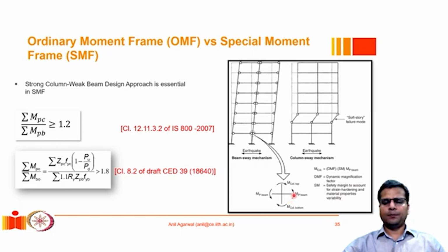The moment capacity of the two beams combined should be less than the moment capacity of the column, so that since the two are going to balance each other, if the beam has a lower capacity, it fails first. We then have to make sure that it has ductile detailing, so that even though it yields first, it does not lead to a drop in moment demand, but allows for larger deflection in the frame, and in return absorbs some seismic energy.